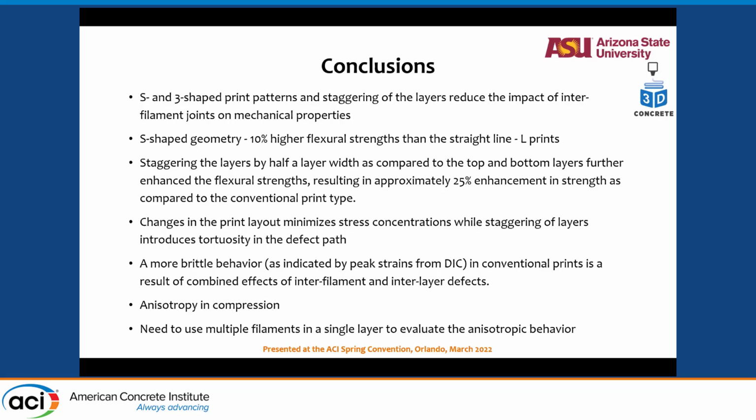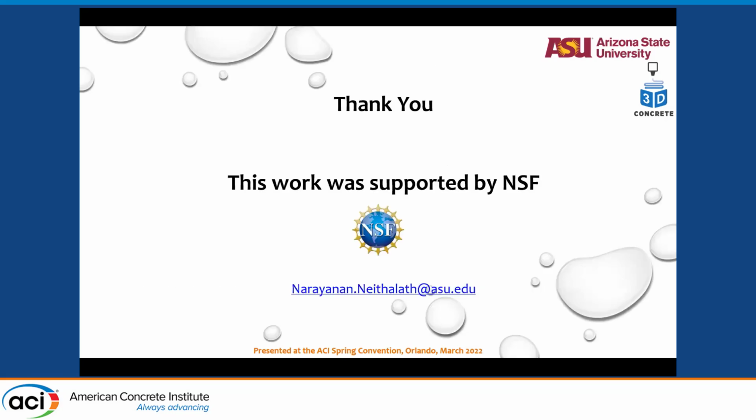A more brittle behavior is indicated in conventional prints. I won't say that it increases ductility, but it increases your peak strengths and peak strain slightly. The overall area increase under the curve is not large enough to call it an increase in ductility, because we typically use ductility in association with fiber reinforcement. But you definitely see that effect. And a combination of fibers and orientation effects is definitely useful. So thank you very much, and I can take any questions.